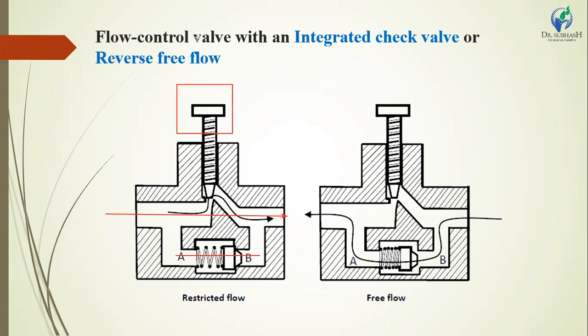First we have to know all the components. This point is an adjustable screw. We can move it clockwise and anti-clockwise for the requirement of flow control. This portion is a screw which moves from inside to outside in the FCV body. This line denotes the body part of the FCV.